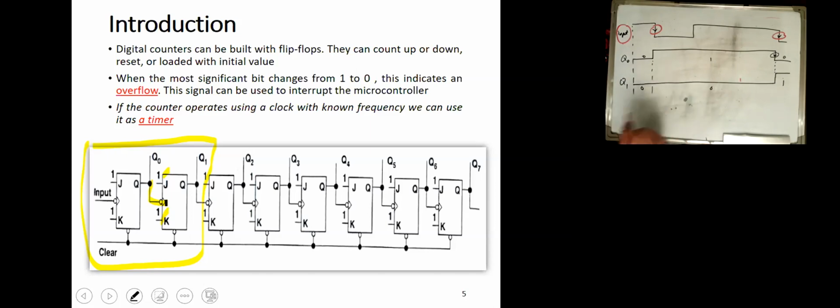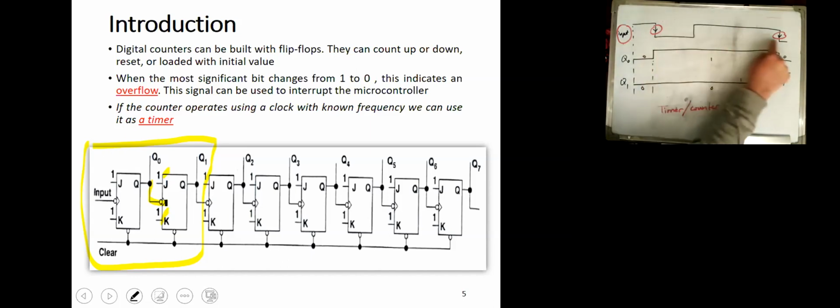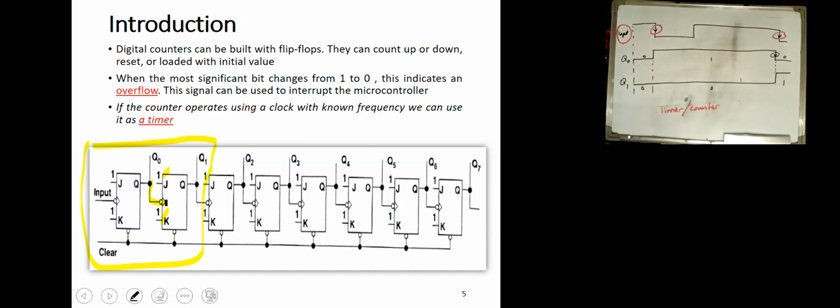That's why if you go to most microcontrollers, the counter or the timer system or the timer module is usually called timer/counter, because you can operate this circuit, which we have on the slide, as a timer to measure time, or as basically a counter to measure asynchronous events or aperiodic events like this.